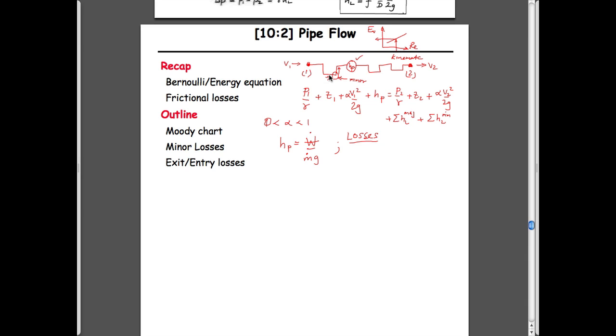And so that won't have changed. But since velocity really is a vector quantity that has both direction and magnitude, its direction has changed. So we've had to accelerate it to get it around this corner. And by accelerating it, presumably we are using up energy to change it from one state to the other. And so we get minor losses related to that.